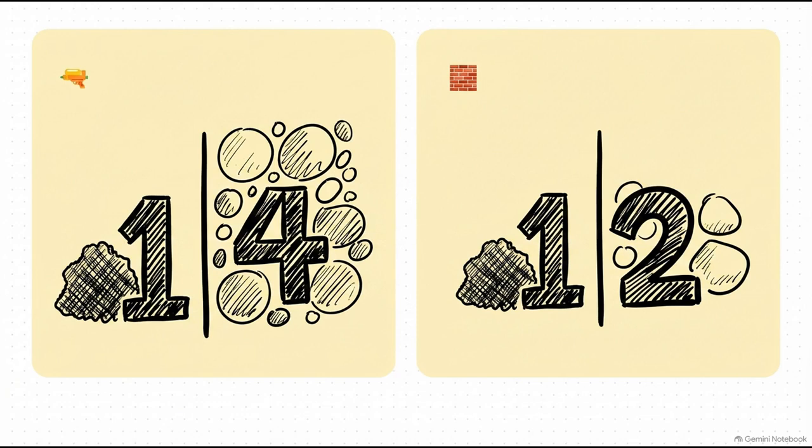Now, let's talk proportions, specifically for the dry mix process. It's fascinating how rebound significantly changes your ratio. Picture this. A traditional dry mix might be perfectly proportioned at 1 part cementitious material to 4 parts aggregate when it goes into the gun. But think about what actually happens on the wall. It can end up closer to a 1:2 ratio once it's in place. Why? Because a huge amount of that coarse aggregate just bounces right off the surface as rebound. As an inspector, it is absolutely crucial to understand that the mix entering the gun is not exactly the same mix that ends up staying on the wall.